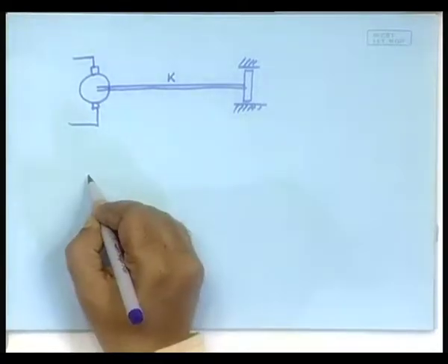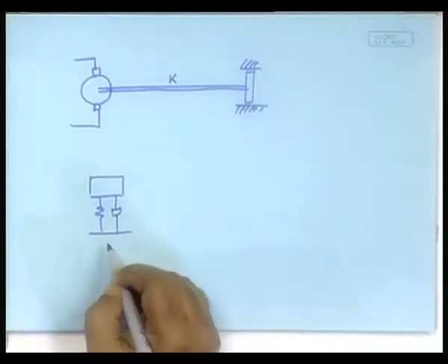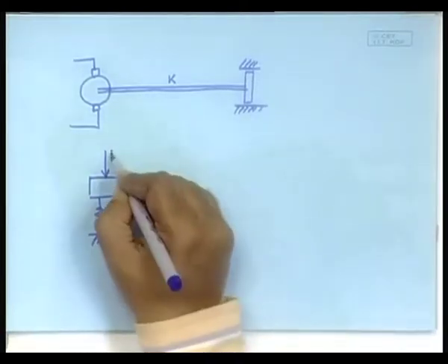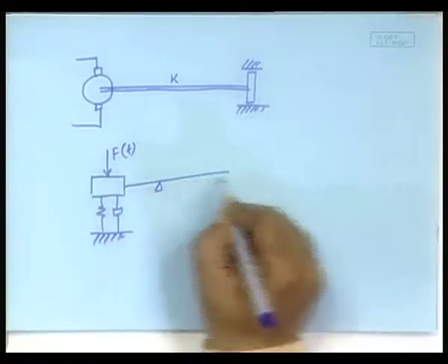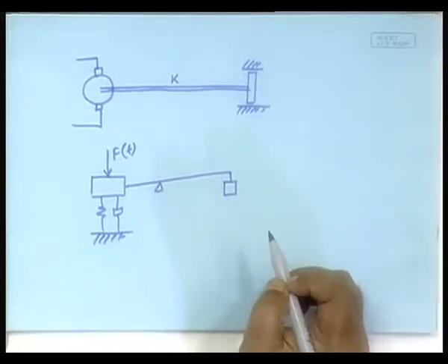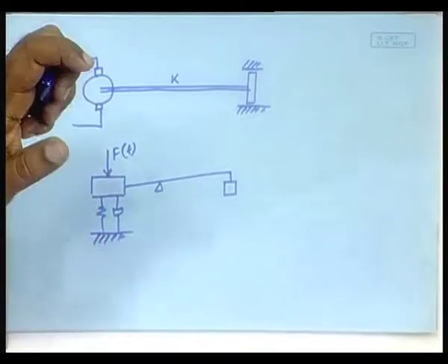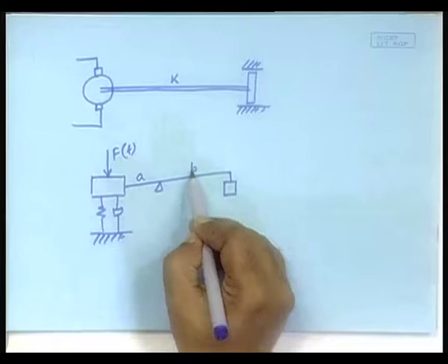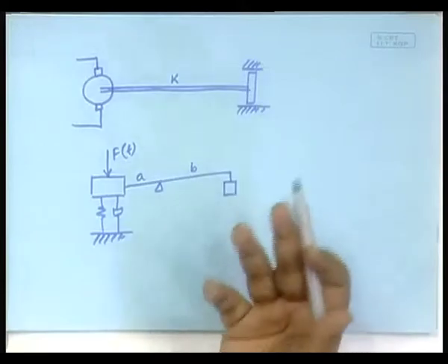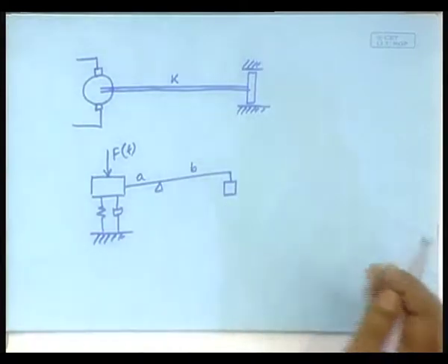Imagine the situation where you had a mass with a spring damper arrangement here and anything there. And now suppose you have a mass directly connected here, then what happens? These two masses, though they apparently are located at quite different places, do not have their own degrees of freedom. Why? Because if this fellow goes up and down, this fellow will have to go up and down exactly in the same way, right. So, they do not have any independent degree of freedom.